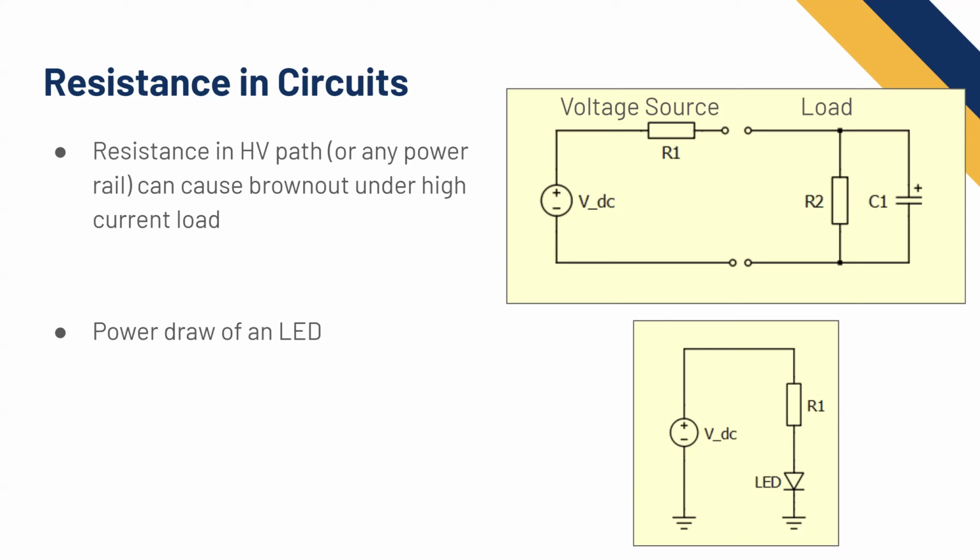You can also think of it in the other way. How much current do we want to go through the diode? And then you look at the diode data sheet and you're like, okay, because the voltage drop changes a little bit, that's a bit more of a nuance, but what current do we want to go through here? So what you would do is you would go look in the data sheet at the graph for how much current, for how bright the LED needs to be. They have graphs for that. So let's say in this case, it's like 4 milliamps.